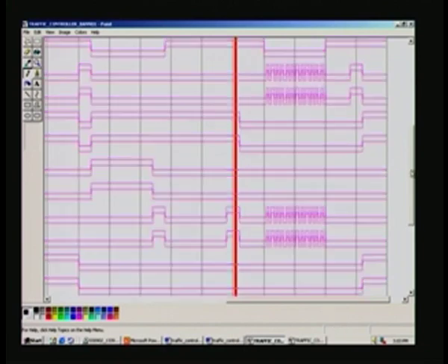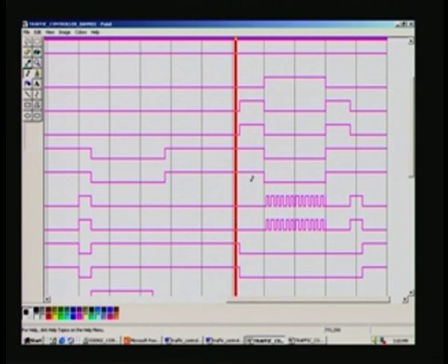And in fact, while doing this, I made a mistake in including the counter. I had explained earlier counter 1 as well as 5. So, I had to take into account counter 1 also, but I did not. As a result, there was ringing here right at the rising edge of each pulse as well as at this edge, and that was because this counter 1 is a much faster counter, and every time counter 5 goes to 9, counter 1 can be anything.